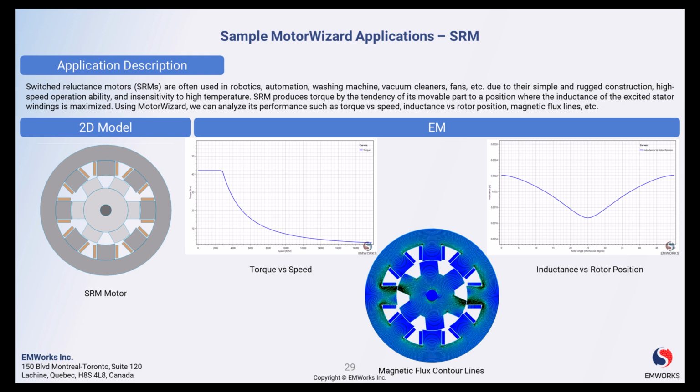Moving ahead, next we have a MotorWizard application that designed and analyzed a switched reluctance machine by simulating torque profiles, flux distribution, inductance characteristics, and more. The insights helped refine the geometry to achieve higher torque density, reduced vibration, and improved control performance.